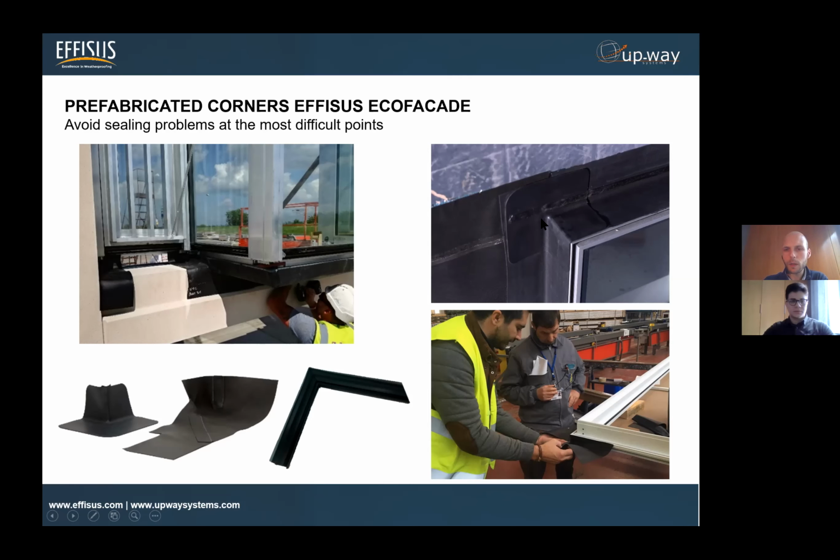the CP board, you might find some difficulty when you reach the corner, and you know that in every window we have 4 corners at least. We may find some difficulties here because we just need to cut, and this will be a weak point, as you for sure understand. So some part of the membrane has to move straight forward to here. The other part will turn into the top of the window here, and the membrane that comes from the horizontal will do exactly the same way, and then you have a leakage point here.